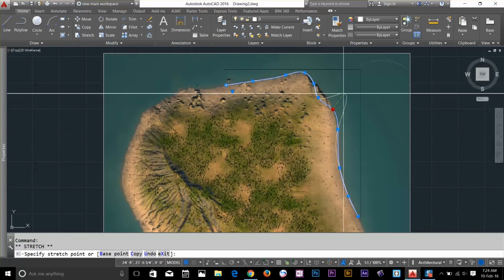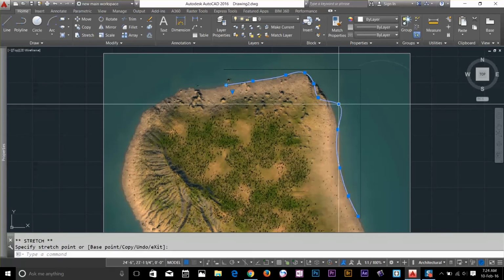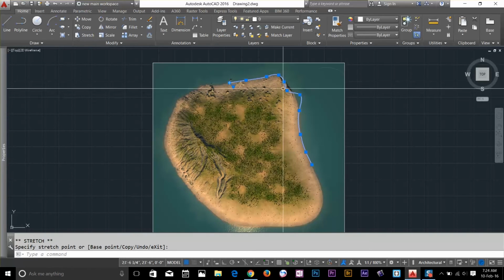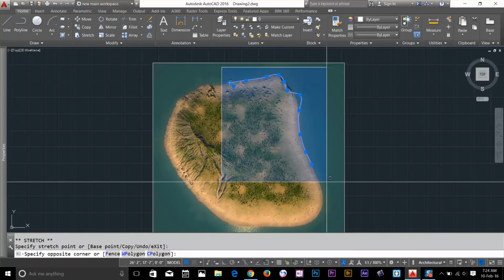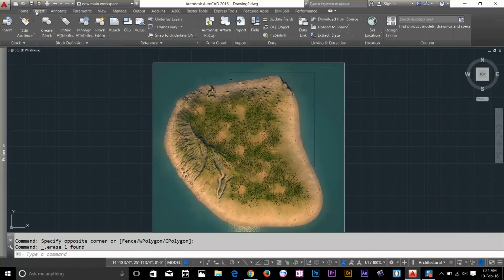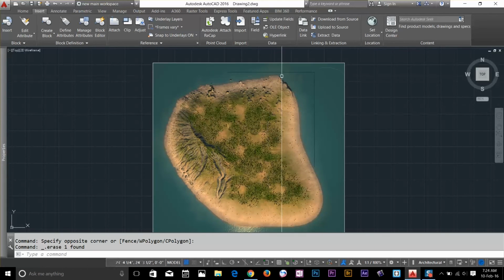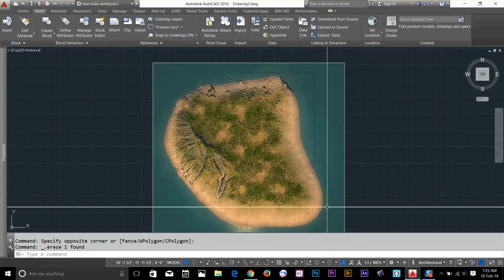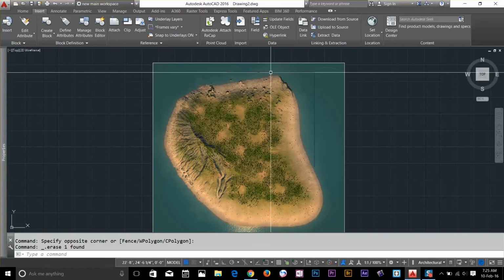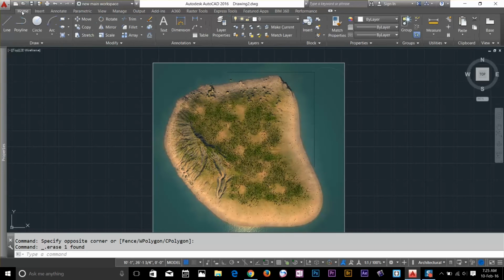I can even remove my fit point, and I can stretch, which is basically a default command after gripping these vertices. So pretty much that's it. You can use spline to trace your islands or any drawing, any JPEG files. So now you know how to bring JPEG files in there to trace the boundaries. Are you making a 3D model and you want to trace those pictures? You can do that as well. We will look at those options later in the course, but now this is how you can use spline.